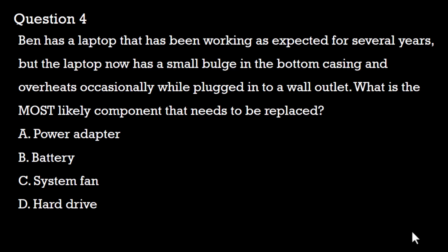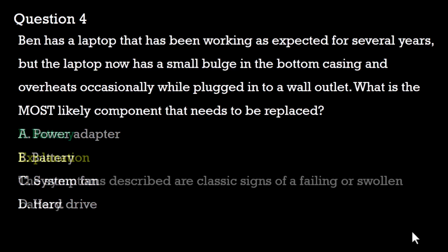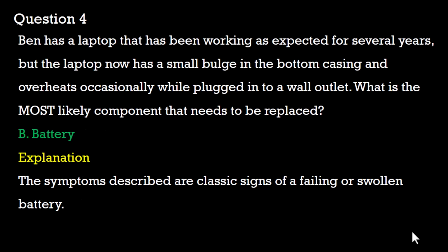So in this case, the component that is most likely needed to be replaced will be option B, the battery. The symptoms described in this scenario, where there's a small bulge in the bottom casing and overheating occurs, would be a classic sign of a failing or bad battery.